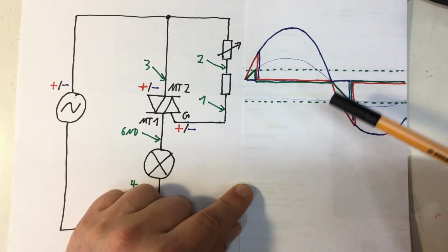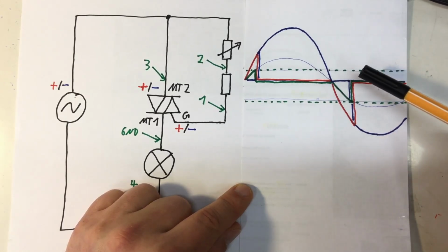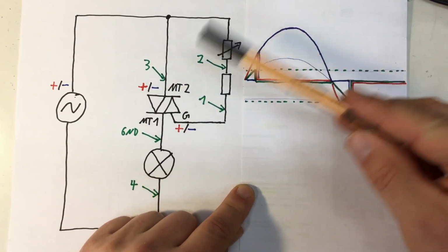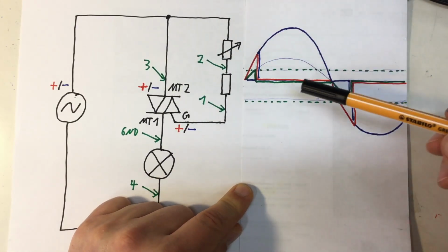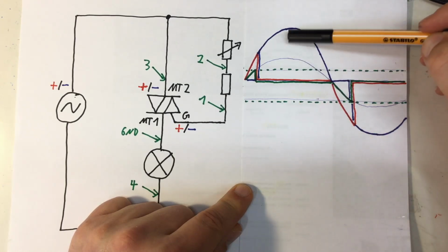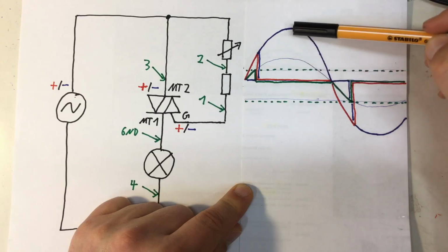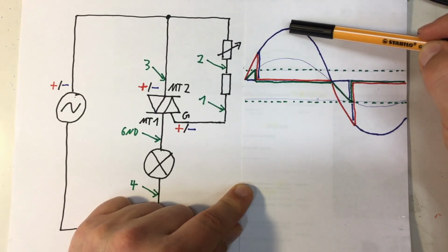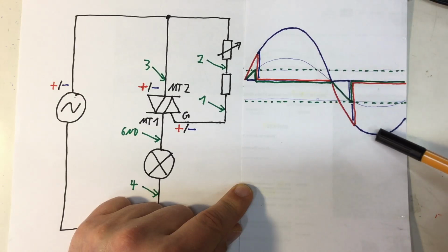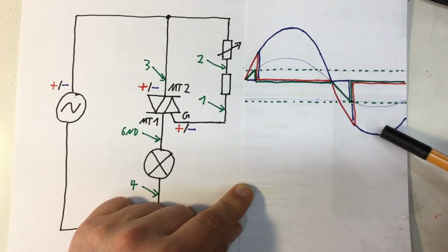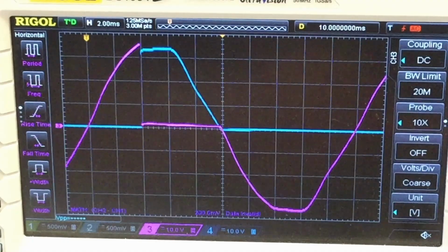Yeah, it's that simple. And also in that regard, using this circuit here, I of course will never be able to switch it on later than here 90 degrees when I'm at the maximum of my trigger current, or at 270 degrees when I'm here at the maximum of my trigger current.